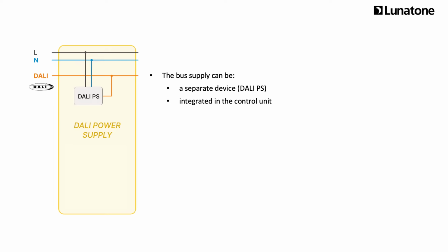According to the DALI standard, it is also possible to integrate a DALI power supply in a control device. This is often seen in local sensors or DALI gateways. However, Lunatone supports a modular system. Therefore, with a few exceptions, the DALI power supply is usually a separate module.